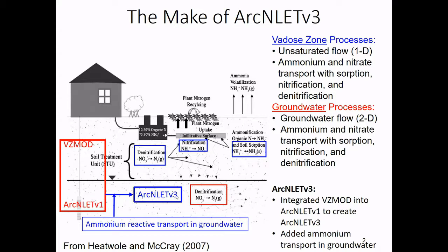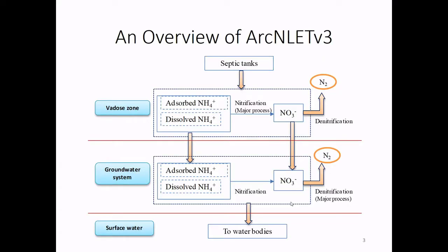And also we add ammonium reactive transport in groundwater. So it's not for nitrate only, it's for both ammonium and nitrate, so that we can simulate ammonium and nitrate transport from drain field to water table and from water table to a surface water body. So I'm gonna talk about the theory first and then give you a demo.